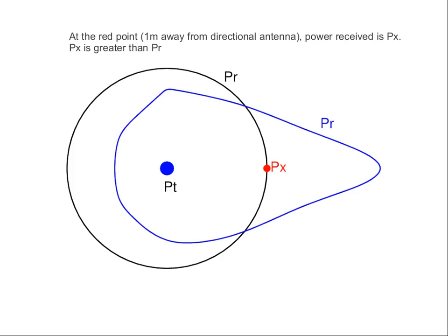Now, of course this is on a geographical map, that is the distance between the transmitter and this point is greater than from this point to here. So, what can we say about Px? It's less than 4 watts and it's more than 1 watt. Okay? We cannot say any more the exact value, we don't know yet. But of course it will be less than the transmit power because again our signal attenuates across distance. It's got to be less than 4 watts.